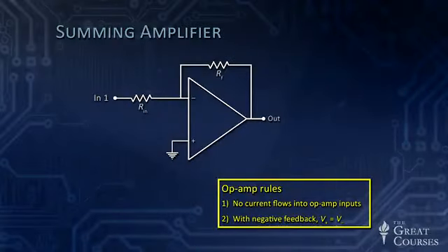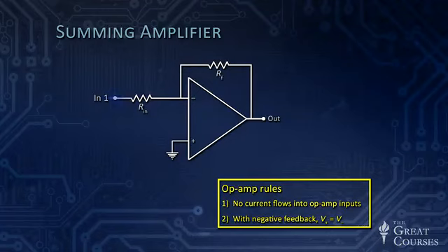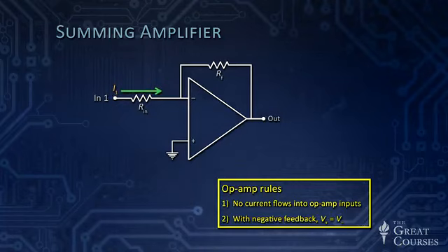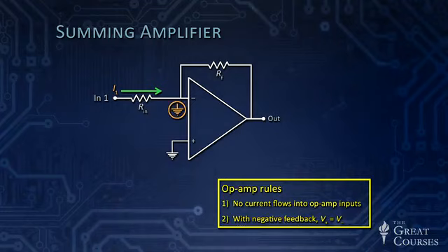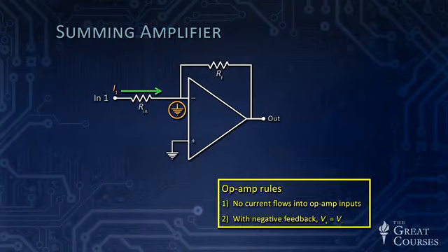So here is an amplifier called a summing amplifier, but it's not a summing amplifier yet. It's simply the same inverting amplifier we've just been talking about. I've drawn it with an input voltage. I'm calling it in1 this time because we're going to have 2 inputs. There's an input current. I'm calling I1. The current is flowing to virtual ground. It isn't really flowing to ground. It's going through the feedback resistor. But as far as that input resistor is concerned, its right end is basically connected to 0 volts to ground.